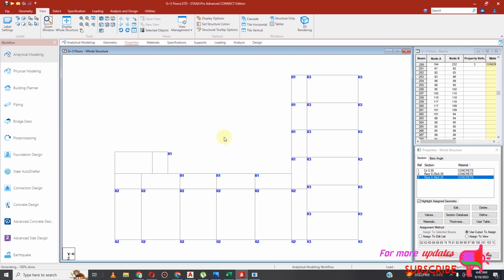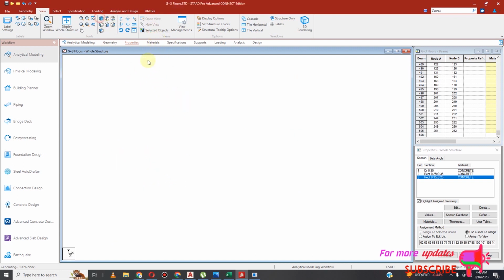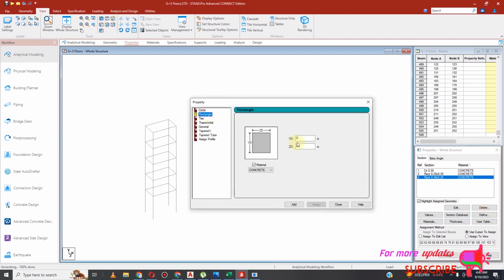So we select our water tank. So water tank columns are different type of columns. So column type 3. So water tank should be a bit bigger in size, because they not only carry the water tank but also the staircase. So 0.4, 0.2, 0.225, then add.